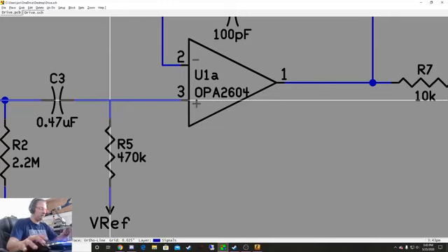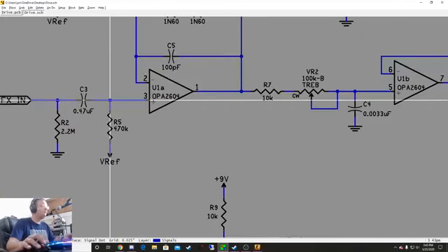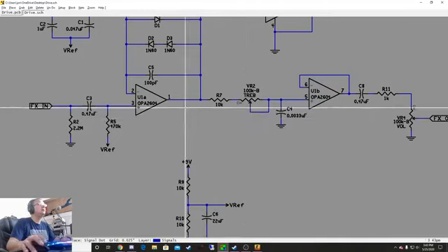And I'm going to do PD to place a dot. A dot means connect those two points. So if I don't dot it, it may or may not be connected, depending on multiple factors. So if you want to be sure it's going to be connected, put the dot there. Yeah, I'll go into more of that in future lessons, but that's a quick rundown.